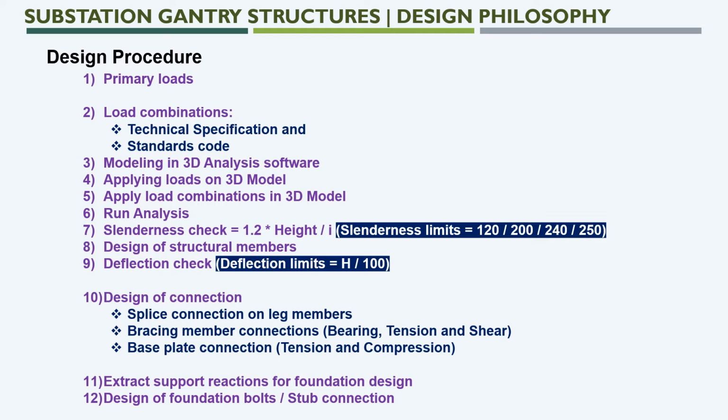So if your structure member is going to be higher than 6 meters, we also need to consider the transportation of the maximum span, because if the project is going to be constructed in a hilly area, the transportation logistics are very difficult. Whereas if there is a narrow way, we need to check that also. So accordingly the splice connection is to be provided for the main legs.